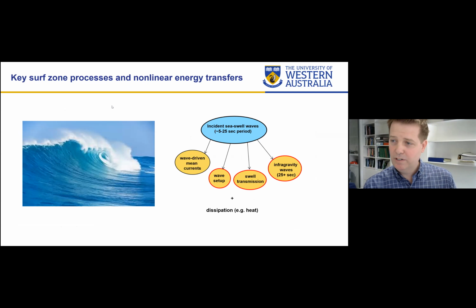And so really all of this is underpinned by understanding these energy transfers and these processes that occur in this narrow, really violent, energetic surf zone, where the energy that's feeding these processes is really driven by your incident wind wave energy. So you see swell waves typically between 5 and 25 seconds. But when those waves break, that energy is not lost. It's not truly dissipated as heat.